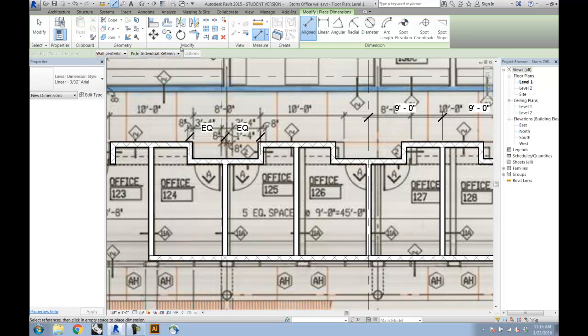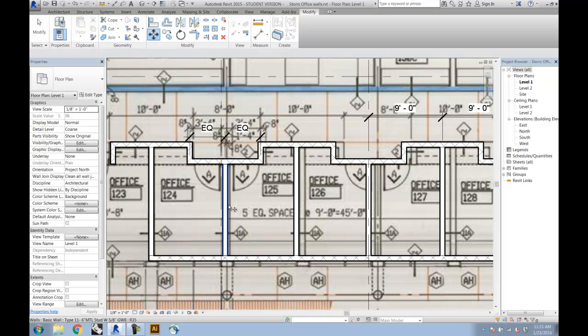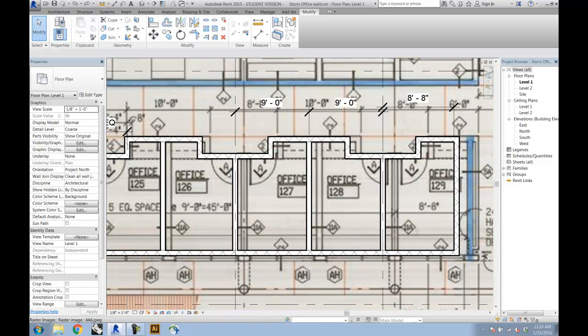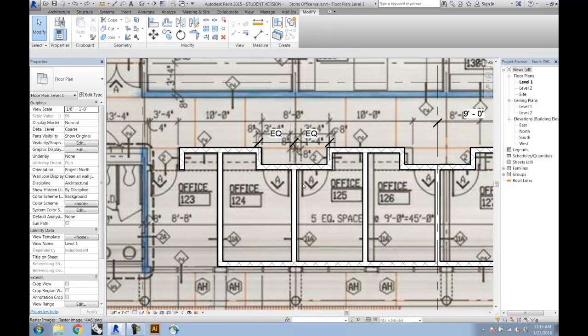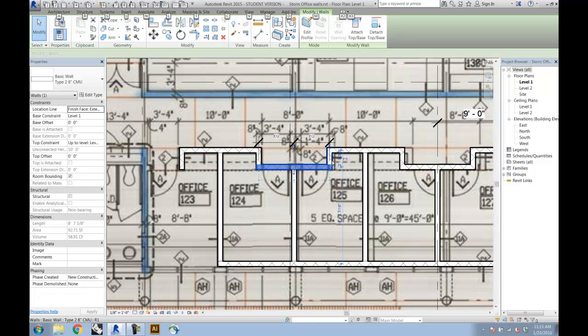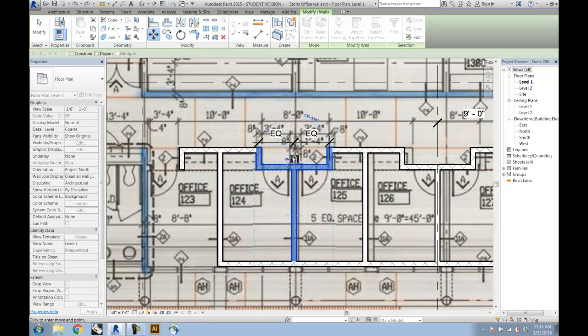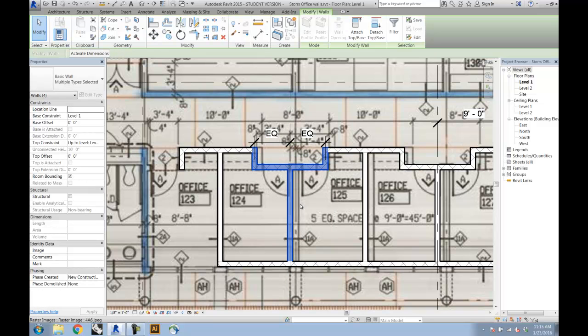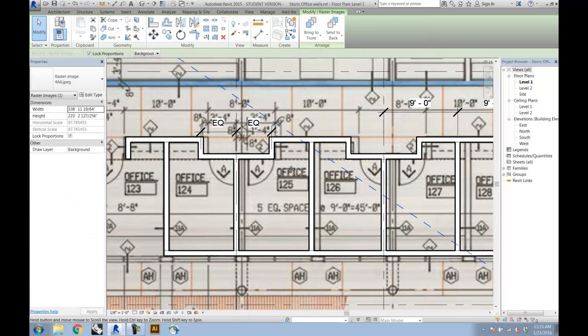One more time, this wall, we need to move first to move it onto the center, and I want to maintain the connection. Holding control, gonna select those, and then snap this wall. Try that again. Holding control, select all these, hit the move button, move center line of that wall over to my grid line.